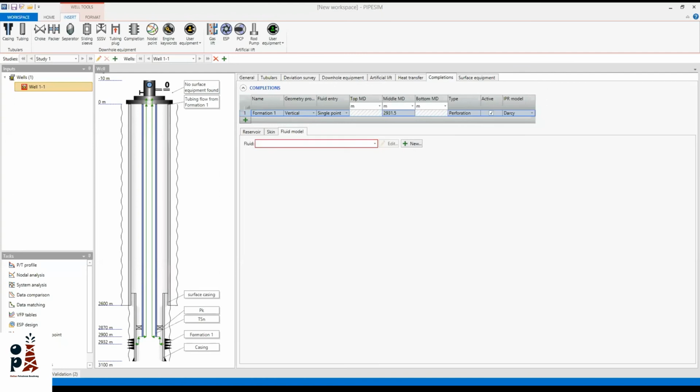Anyway, I will put in my parameters. The exercise said that we have a pure oil, so the water cut, or the percentage of the water volume of the produced reservoir fluid, is 0. The gas oil ratio is 386 from the test on an offset well producing from the same reservoir, and the gas gravity from the same source will be 0.8, and the API, as illustrated in the example, is 33.86.